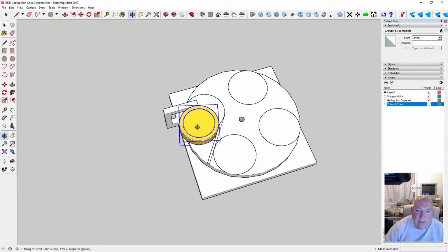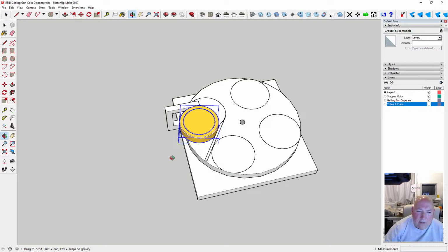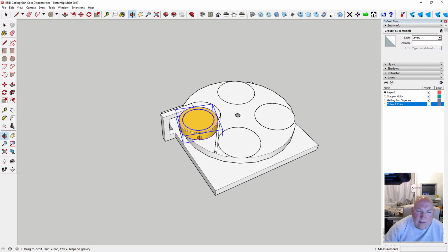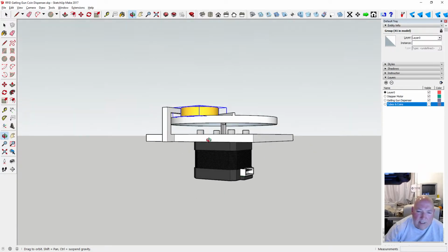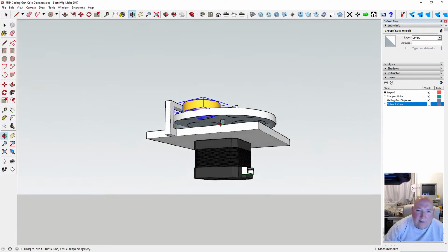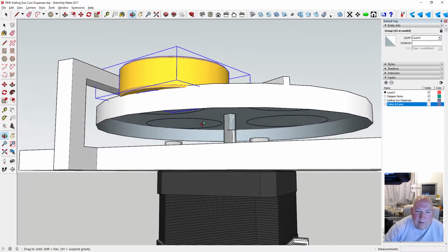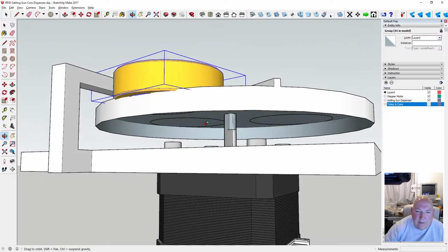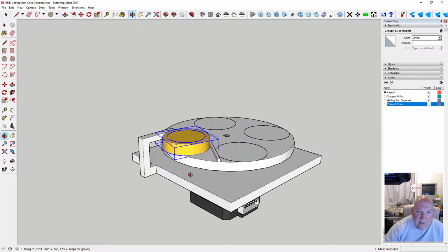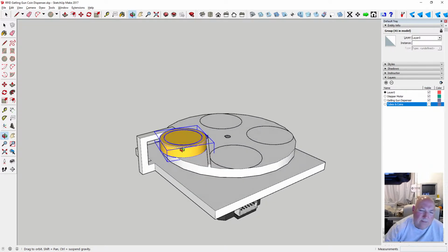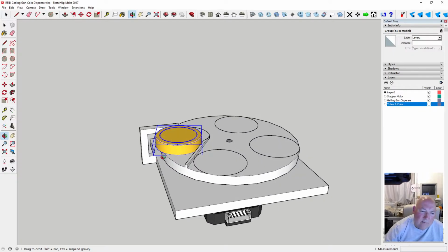Quite slidey, and it's got this V bit, and it's only lightweight, so it's going to push it out. If I need to, I can make the stepper motor oscillate slightly. Oh, I've lost my surface. I'll put that back after. So with the stepper motor, I can make it oscillate back and forth, 2 steps forward, 1 step back, kind of thing, and slowly push this coin out.